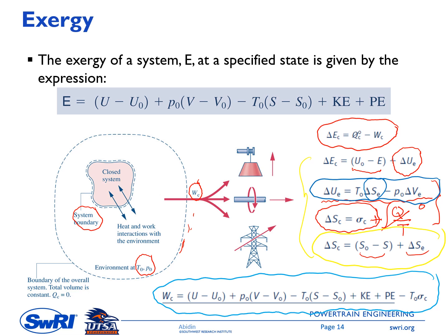destruction. So if you remember, the definition of the exergy is the maximum theoretical work that can be developed when the system comes into equilibrium with the environment. So it means the maximum theoretical work. So it also means there is no entropy destruction in the process. So it means when we have this sigma equal to 0, then we have a maximum work, and this maximum work is called exergy, and it is formulated here. So this formula actually is this formula when the sigma equal to 0. Okay.